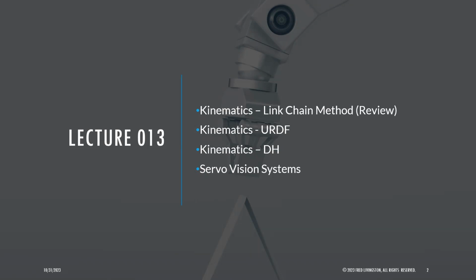A lot of robot systems can't do 360 degrees. They have limited motion, so you can put those min and max joint limits into the system, and you compute a solution within those limits. DH is more like a script: you read in your DH table, which is your A matrix for that n-degree-of-freedom robot. It allows you to have the same code base, and you just upload the DH for that particular robot and get the configuration for it as well.